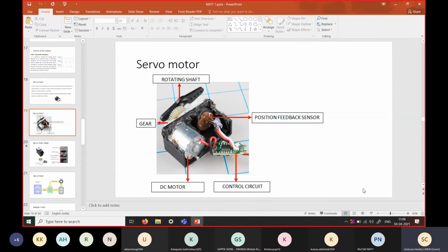Now we are continuously communicating to the servo controller that we need to maintain 90 degrees, even when external disturbances are present. Suppose it reached 90 degrees and stopped, but due to some external torque the shaft is moved from 90 to 95 degrees. Again the controller will automatically bring the shaft position back to 90 degrees.